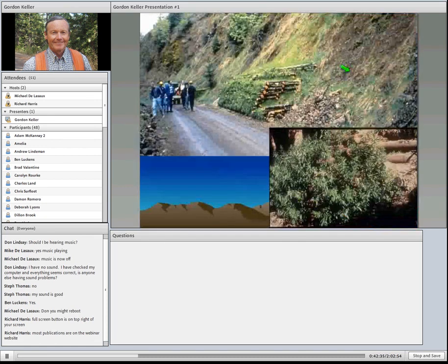And then we get the true biotechnical structures. It's interesting, I look at these because some of them seem like little figures are missing. But anyway, this is a live crib wall. This is in the North Coast. This is down in the Bay Area with eucalyptus, I believe. But anyway, it's combining a physical structure with vegetation, so you're getting the best of both worlds. You're getting the physical structure, and you're getting the long-term root support from vegetation. So that's why biotechnical treatments are so nice, and they're aesthetic, very appropriate for certainly shallow to moderate failures.